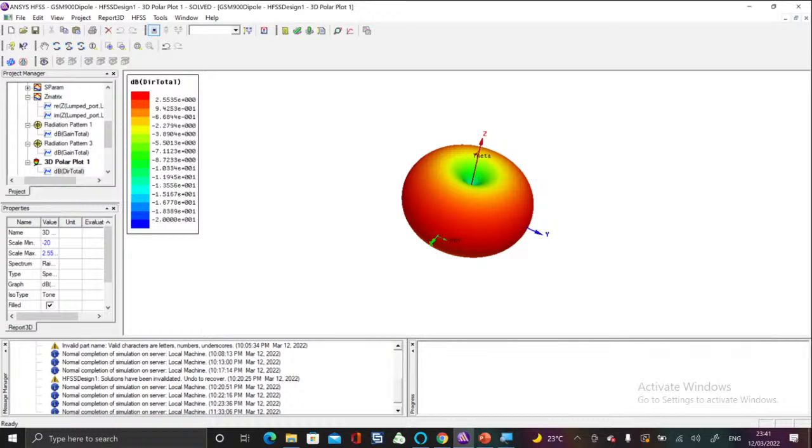And you can see a more clear radiation pattern. The green part shows you that there is no radiation along that. The red part shows you there is maximum radiation. So green to yellow to red shows how the radiation changes as you move from the antenna orientation towards the broadside, how the gain or directivity changes, that you see through this radiation pattern.